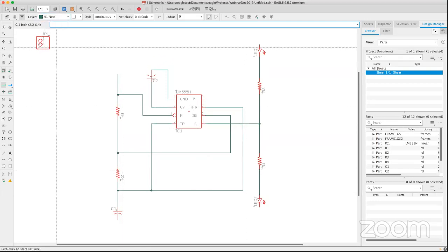Now, Eagle does have some libraries that only represent power. In other words, they absolutely have no contribution to the circuit board design at all. They're only used as rails or to distribute power or to distribute a particular signal. In this case, it's usually power, to distribute power throughout my design.